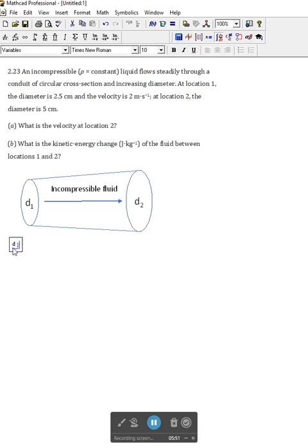Now I want to assign the value 2.5 centimeters. And so to assign values in MathCad, you use shift semicolon or colon basically. So you press the shift key and the semicolon colon key. And you see that gives you the MathCad assigning a variable sign. And so now I'm going to type, you see the cursor here, 2.5.